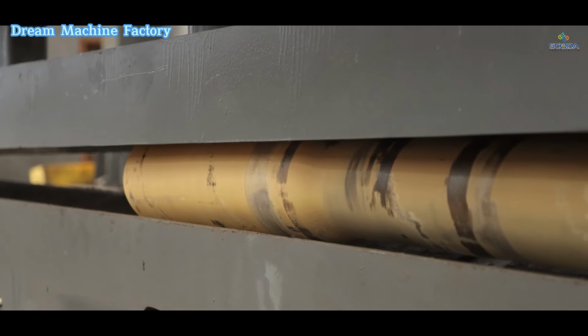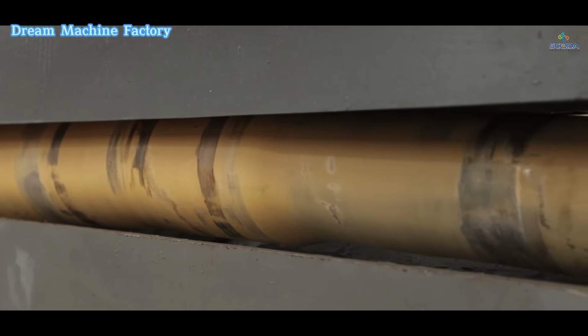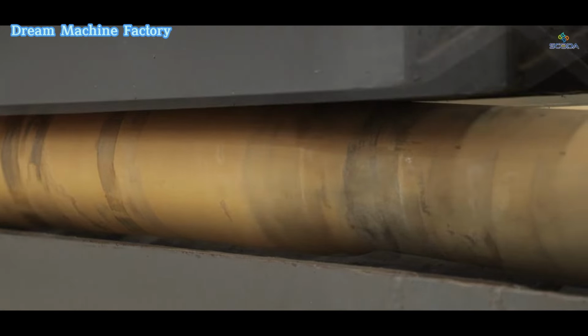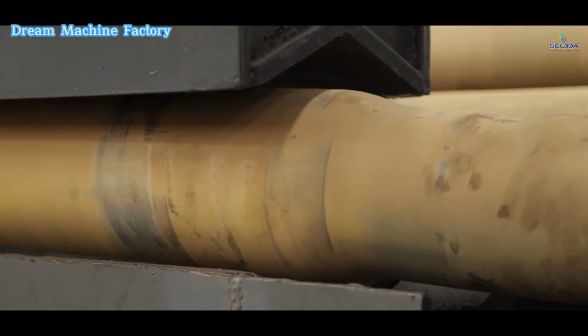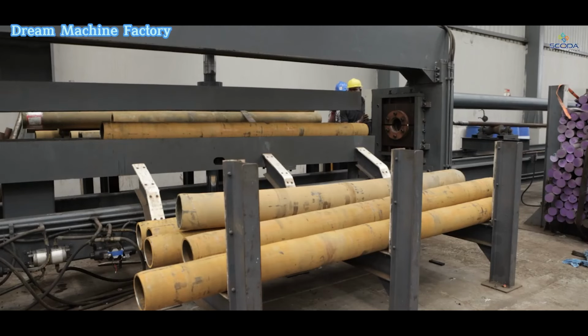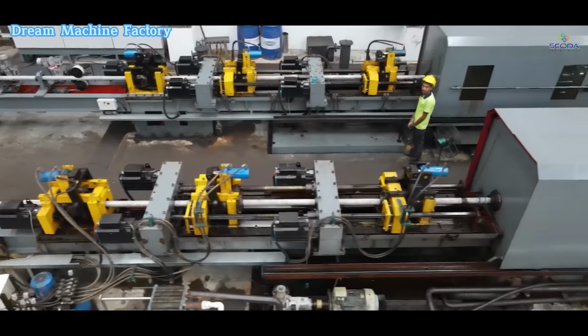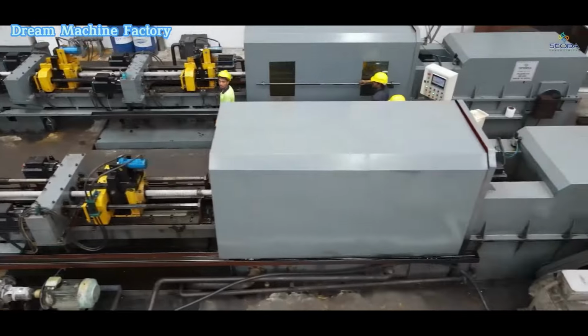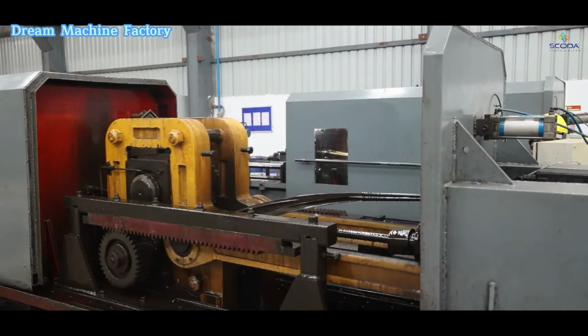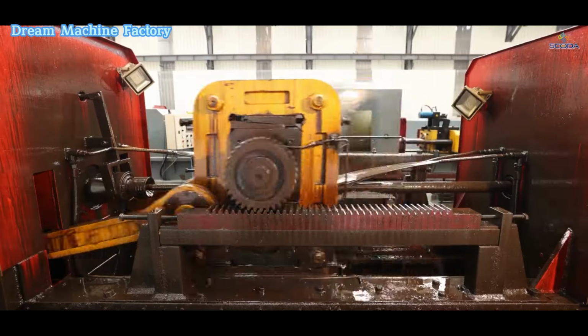Straightening corrects these deformations. The process typically involves passing the material through a straightening machine, which uses a series of rollers or pressurized rolls to apply force at various points along the tube. These rollers gradually reshape the metal, restoring it to a straight configuration. Straightening is crucial for ensuring the material is uniform in size, ensuring it can be efficiently processed in further steps like coating, cutting, or welding.